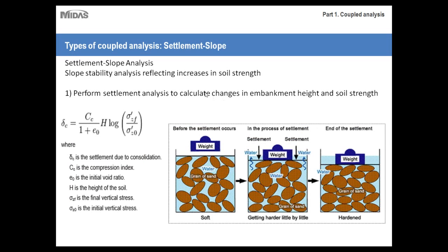Okay, and now let's talk about settlement analysis. The first thing that we need to discuss is the basic principles of settlement. I'm sure you're all familiar with consolidation, but as a recap, consolidation is when, for example, you have a clayey soil that's subjected to a certain amount of weight. Because the pores in clayey soil are so small, water takes a long time to escape from those pores when weight is pressed upon it. Depending on how resilient, how strong or how tightly compacted your clay is, this could take any number of days or even months.